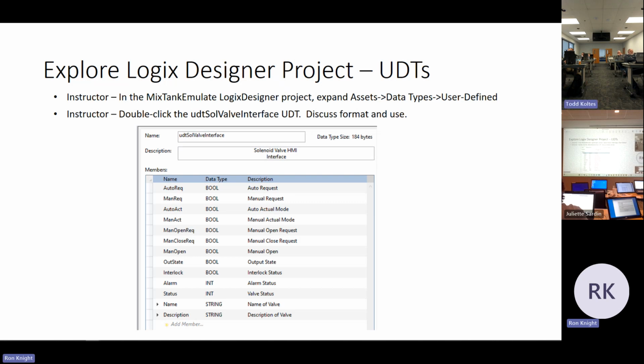Likewise, if we're going to monitor and control that valve from the HMI, and let's say there's around 15 or so tags that we want to be able to read and write from the HMI. In the old days, we would create those tags for every valve, copy and paste them, change the address, copy and paste, change the address. So the problem is, operations comes and says, you know what? We want to monitor torque feedback on every valve. Go and add torque feedback to every valve. Well, we would have to go touch 500 rungs of logic and then come to the HMI and create tags for torque feedback, however many valves we got.